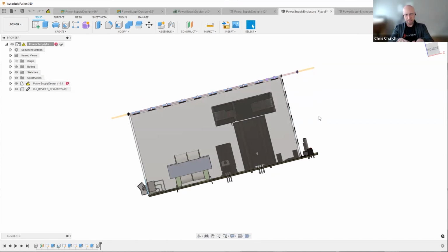So it's pretty long, because one of the things you definitely want to avoid, and this is one of the things our team will be looking out for as we talk about manufacturability, is this: if that fan is attached to that enclosure and then we have to put the PCB on there, we don't want to be in a fiddly situation where someone is trying to reach through and plug in a little connector because they've only got 5 millimeters of space between the two to assemble it. So it's good that that cable is long enough, but it can create some other issues that our team would call out.